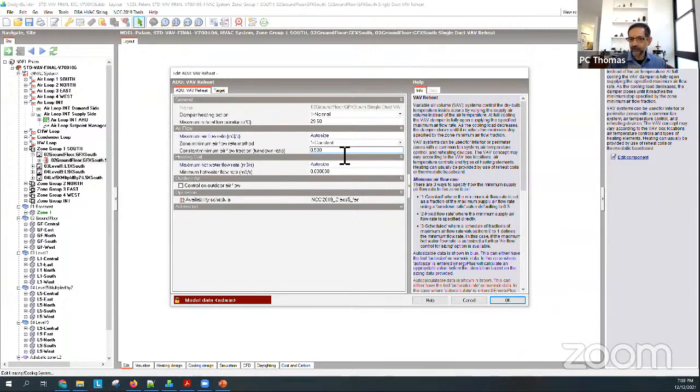Nobody will be able to tell you, so you have to take a guess, or you have to do a detailed design, and somebody has to add up all the pressures and tell you that at that point I need so much pressure, equal to so much percentage of the design flow. Then you can set it. Typically they'll tell you 50%, 60%. That's good. If they start telling you numbers like you can drop it all the way down to 20%, that's rubbish. You get fantastic outcomes in the simulation, but you will never get it in reality.